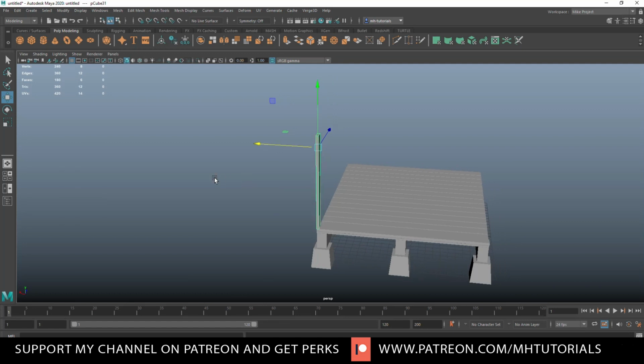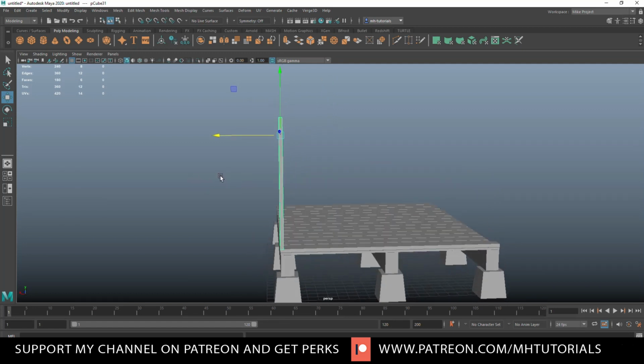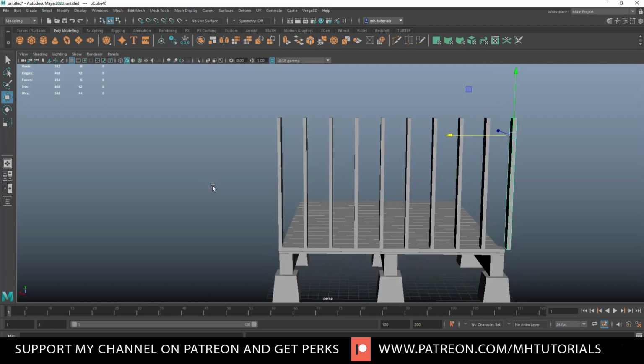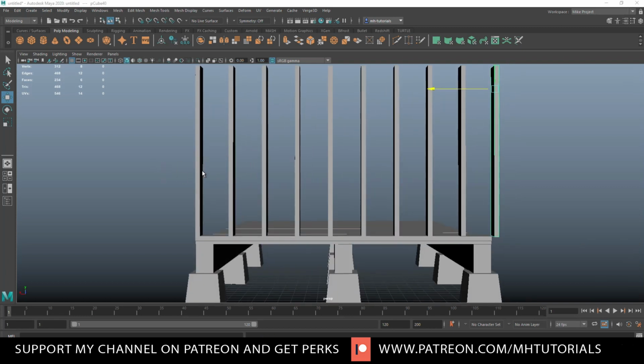All right. And now what we're going to do is copy this guy over. So Control D to duplicate, W to move over. Let's do, I would say about so. And then we're going to hit Shift D and work our way over and see what we need to correct, right? Okay, so what we're going to do here is what we did. Oops. What we're going to do here is drag select these. We're going to go to Mesh and Combine.